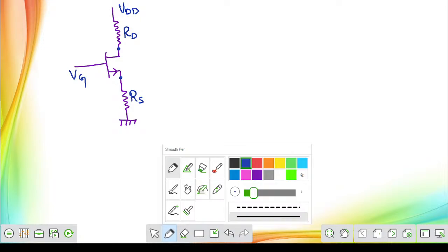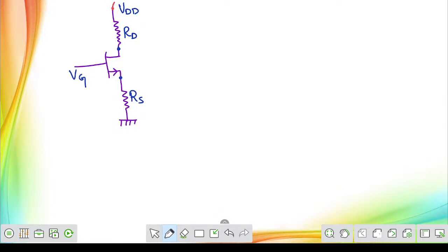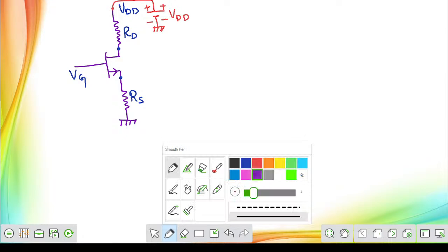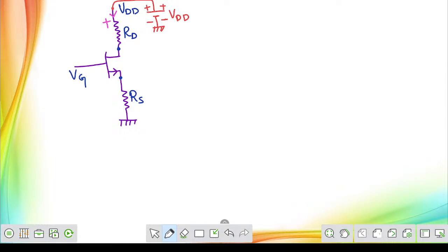Now, if you observe the present circuit and you are requested to cross-check it, what do you have to do? Here, you can apply only KVL. From the top, it is a source, which can be represented like this, plus minus. We can consider it as VDD. To apply KVL, top plus, bottom minus. For the resistor, current is coming in the downward direction. Mark the polarity for the resistor: since the current is downward, the entering point is plus and the leaving point is minus.